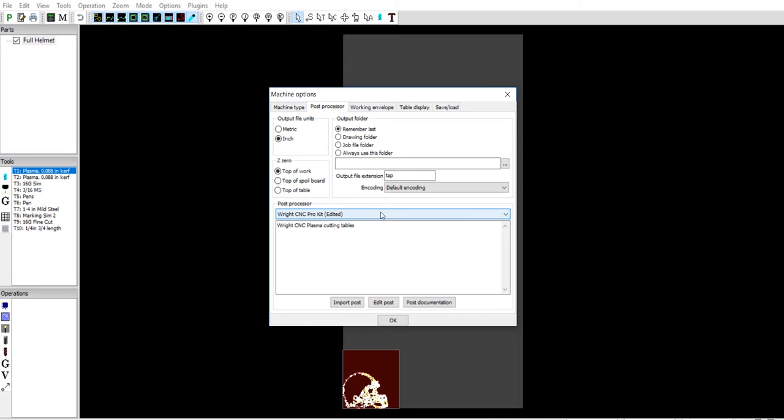All right. And then we have one called a constant touch-off. That is every time the machine goes to make a pierce, it's going to come down, touch the material, lift off, and it's just going to do that every single time, as opposed to this current post-processor, which will do it intermittently throughout the cut based off of a given set of criteria that's coded into this system. So keep that in mind.